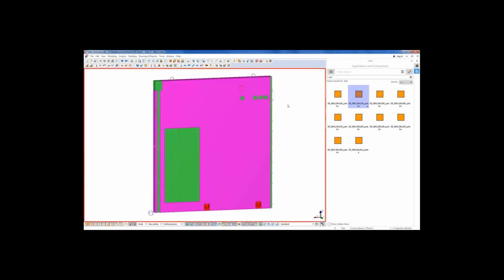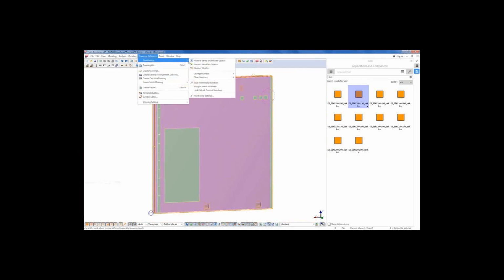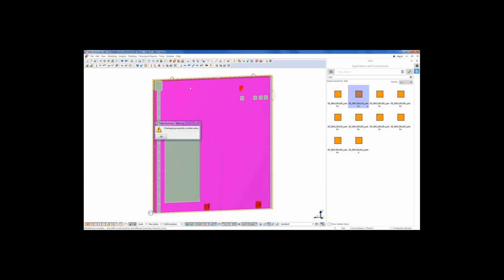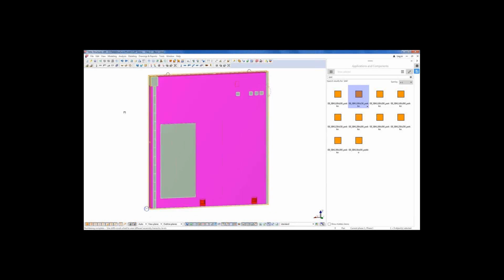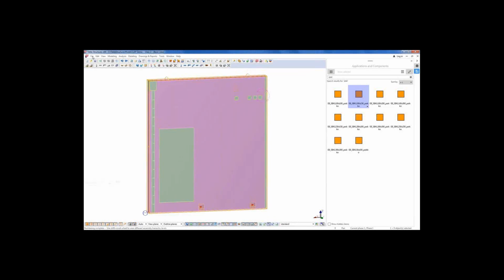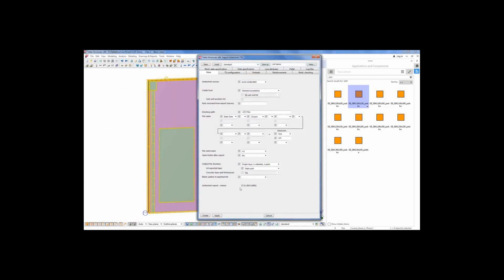So one thing more before starting exporting, we have to number the elements. Start numbering and number the elements. Now once we have finished the numbering, we can select the element and file, export this to Unitechnic file. So everything looks good. Just in case, let's load the settings, apply, create. Here we can see parts exported successfully.